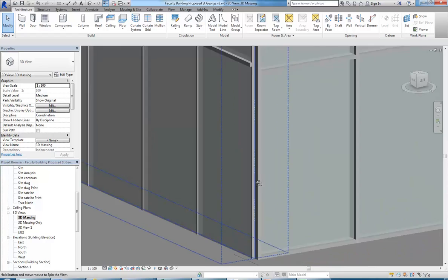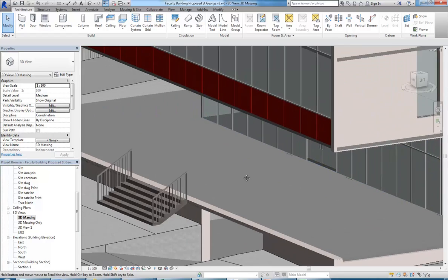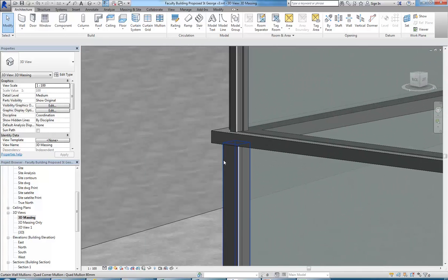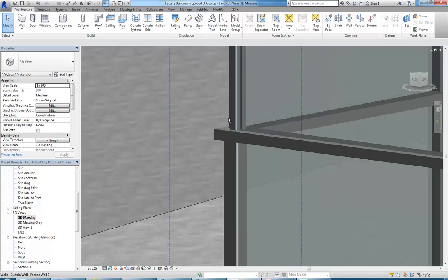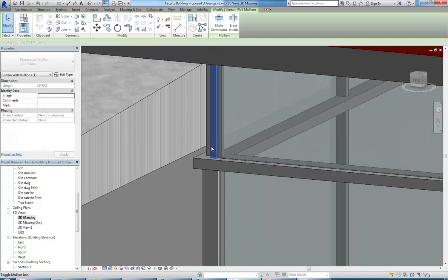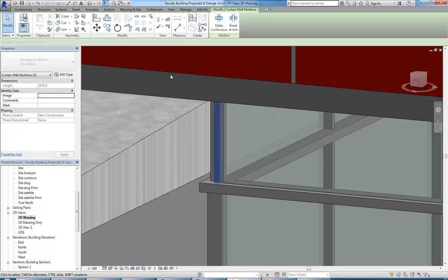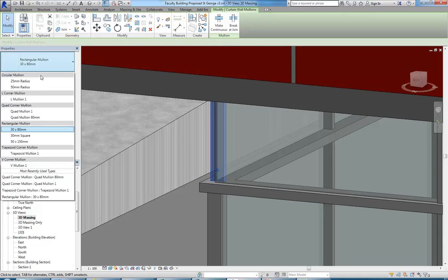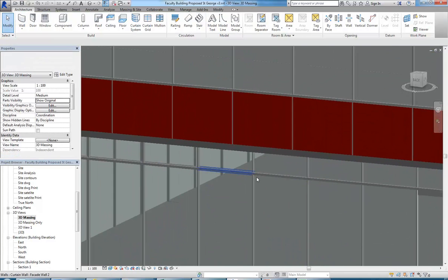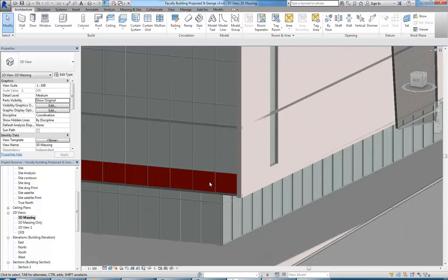So there, I better check the other end actually, just so you can see what I mean. So I did the mullion in plan, the corner mullion, but the mullions that I couldn't see in plan weren't done. So I'd need to go and in 3D adjust those anyway. So I can, again, just select it there, unpin, delete, and then select the other one, unpin, and then change it to the quad mullion I've just made. It's that easy. So that's why you probably do a lot of this work in 3D.